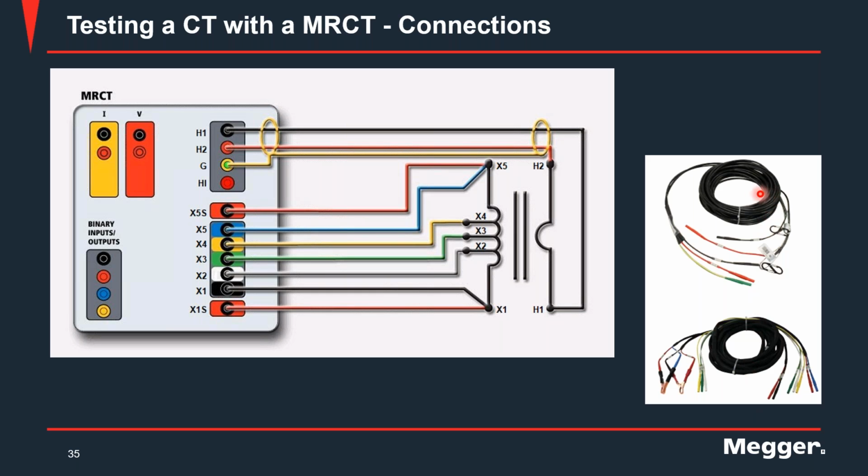The one on the top here is the primary lead. You will see a pair of stress relievers on the primary leads. These are used to make sure that the clamp doesn't slip from the bushing under the weight of the cable. So you'll wrap the cable once around the bushing and run it through that stress reliever, so that takes the pressure off of the connection.